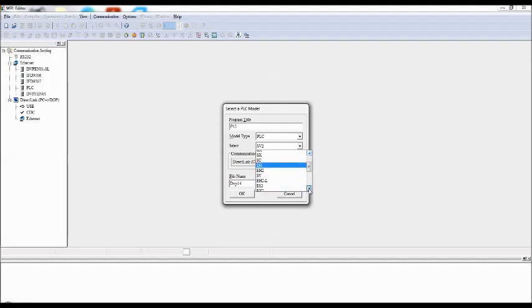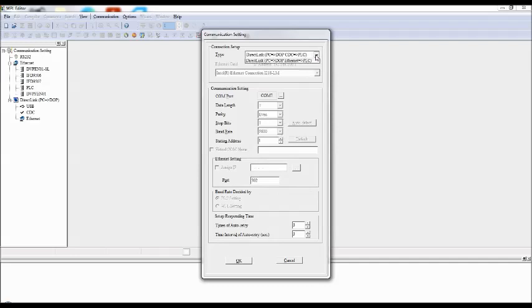We are using 14 SS2 PLC trainer kit, and in the settings, it should be direct link PC to DOP. DOP is nothing but HMI, and CDC to PLC. So this is what the communication type should be. Make sure that RS232 is used only when you are communicating with only PLC. Okay, so direct link, select the last but one option, PC to DOP and CDC to PLC.